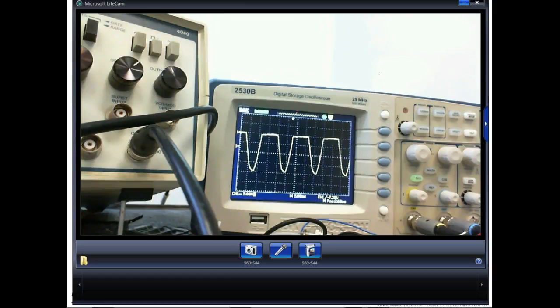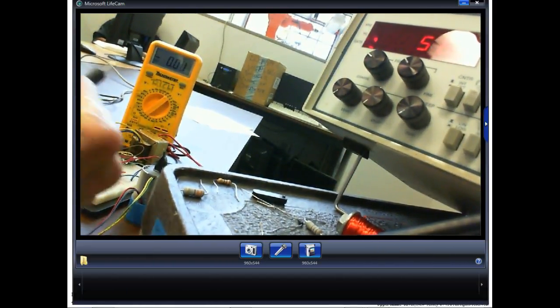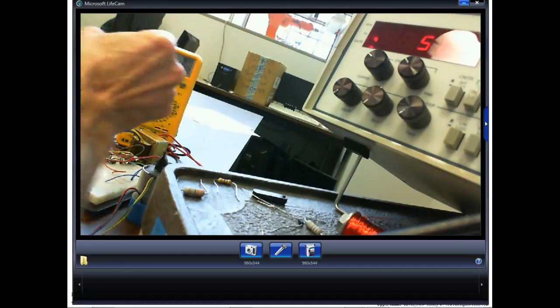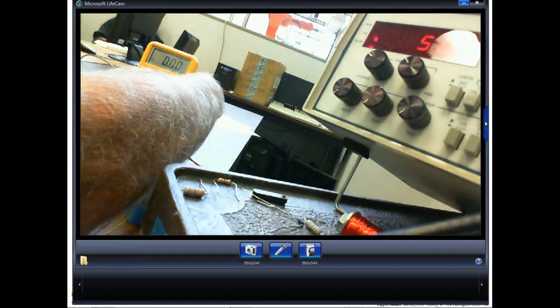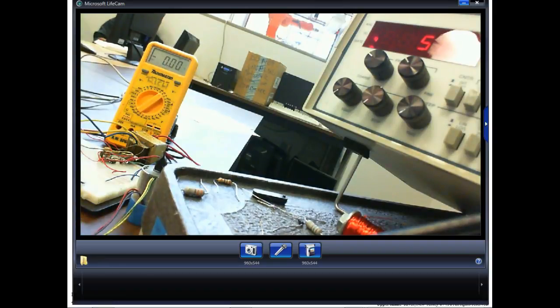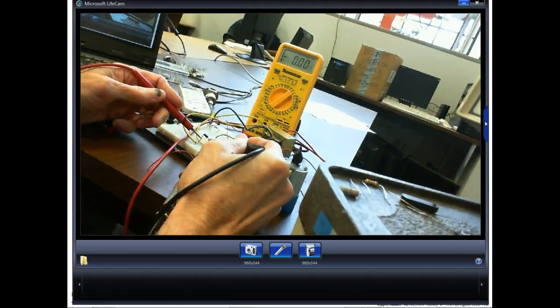You understand? Well, calculating the DC average would be the same. I mean, if I come over here and put my meter and I hook it up the same way, so I'm going to put it on the common at the bottom of my resistor. I'm going to put my meter on there, and now it's measuring a negative 6 point. See, now it's negative, right? You understand? Can y'all see that? Now it shows up better, right? I'm going to put my meter across the transformer. What's it going to measure?